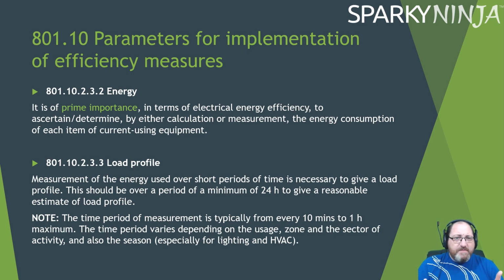If you've done any maximum demand calculations where you've actually looked at a profile of load, there's even an illustration of that, I think, in the electrician's design guide. This is load profiling, looking at the load for a 24-hour period and actually then deciding how to change the characteristics of the system, how to heat the water at night time instead of heating it at the same time as this other equipment. Try to recognize the different loads and time their operation at a place where the overall demand is brought down and they're not all collecting together. That's simple load profiling.